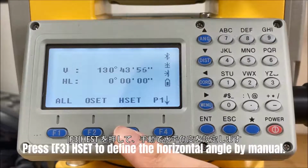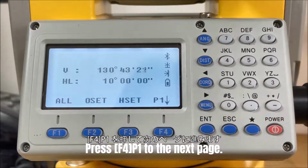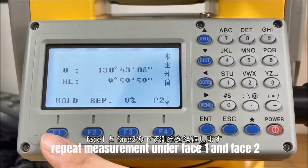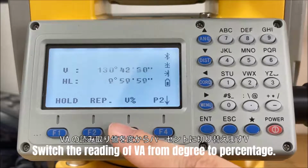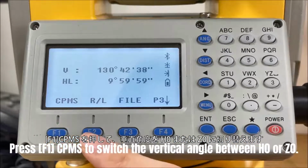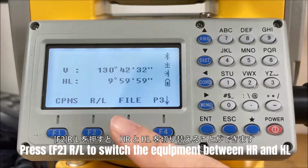Or press F3 to define the horizontal angle manually. Press F4 to go to the next page. Here we can hold the horizontal angle, repeat measurement under phase 1 and phase 2, or switch the reading of vertical angle from vertical degree to percentage. Press CPMS to switch the vertical angle between horizontal 0 or zenith 0. Press RL to switch the equipment between horizontal right or left.